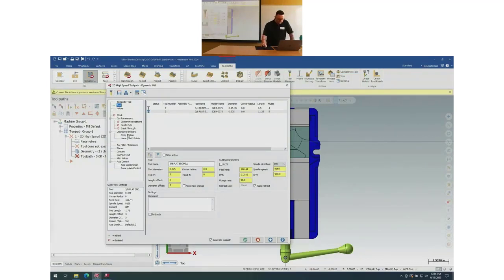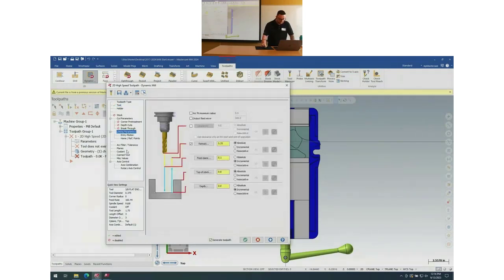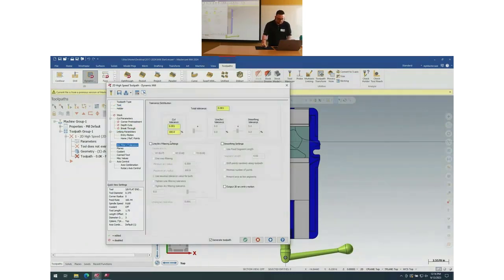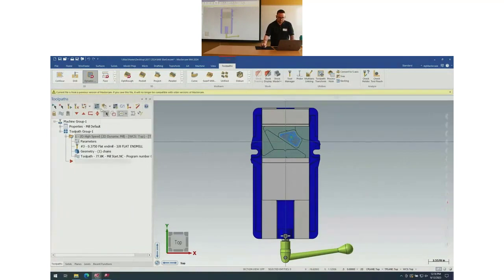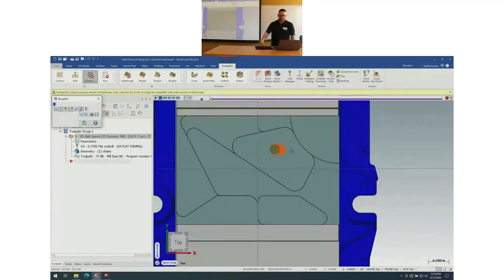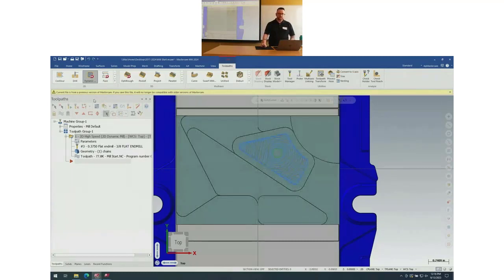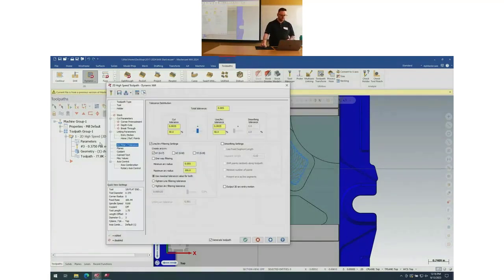And we'll set up a basic arc filter. Same thing, all the other stuff at defaults, again, not touching anything differently. We're going to get a different result here. And so if we run that helix, no post in the middle. Because what this toolpath will do is it will actually look at the tool that you're using and adjust that helix depending on your tool without you even doing anything.